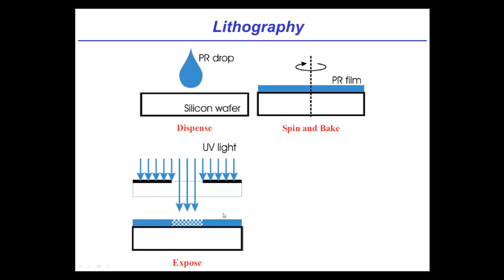So now what we do is we take this wafer, which has now gone through what we call the exposure process, and we develop it. And what we do in developing is we dunk it into a chemical that will etch out one of the regions but leave the other. So in the example shown here, I dunk it into a chemical that etches out the exposed region but leaves the unexposed regions. And so the consequence is when we're done developing, what we are left with is a pattern that to a large degree mimics the mask. And so you see now that we've got a technique to create patterns in photoresist, and then the next step is going to be to figure out how to use this pattern to create patterns on the wafer.